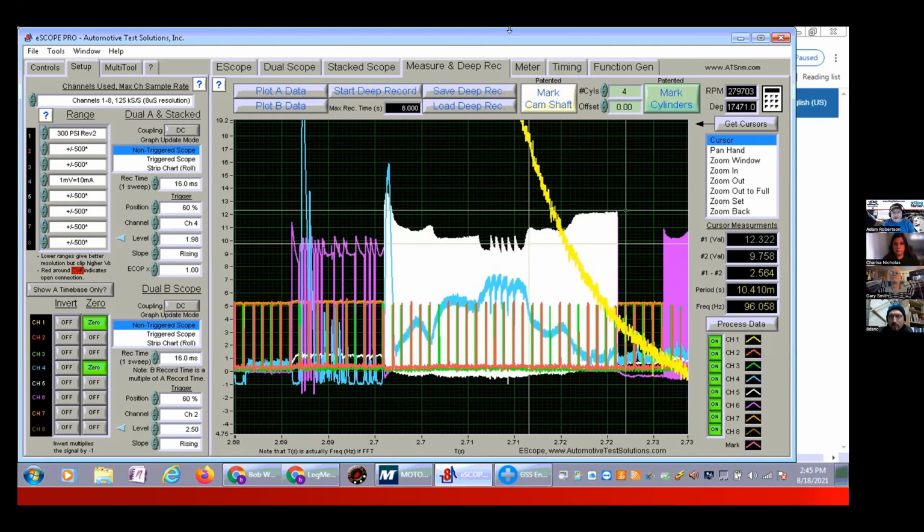We could teach the little dude in the dash to say, hey, we know this is part of the law, and as we see the speed of that come back, that's giving us our speed indicator. Instead of having to put a Hall effect switch on it or truly measure speed, they can really say, hey, we're at 2,000, 3,000, 4,000, 5,000. And it was just software rather than extra hardware to put that speed indicator on that electric water pump or that fuel pump or cooling pump. It's just cool to me.